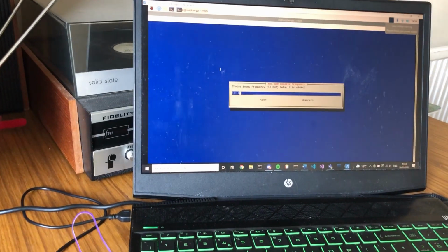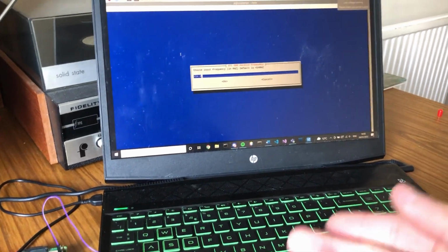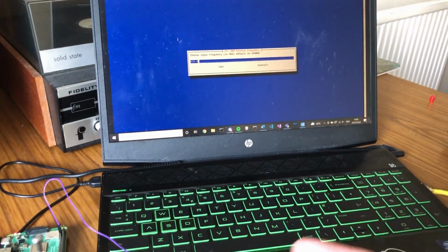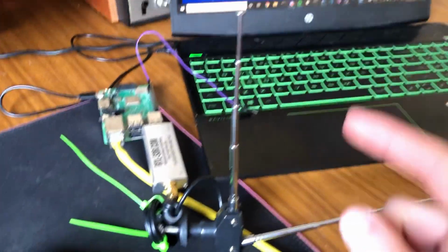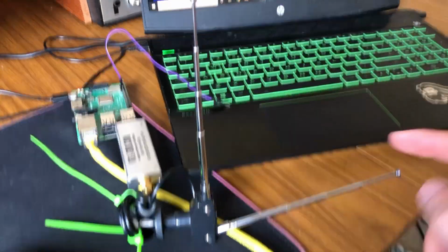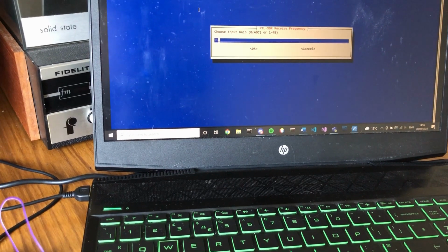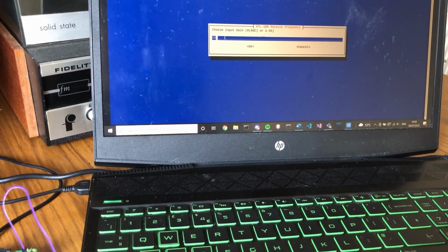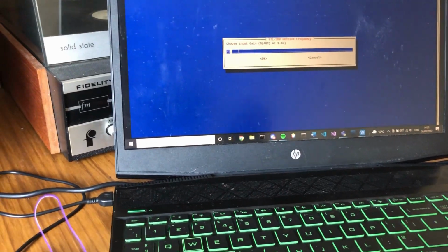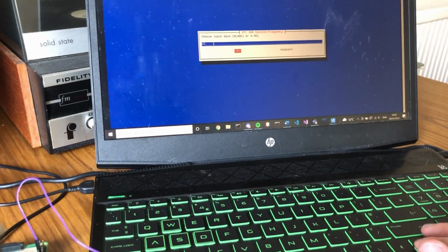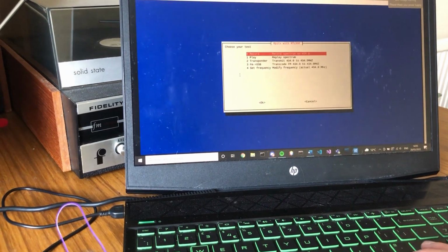And so this prompts for an input frequency. This app basically is the app that captures and records the frequencies we want. So I've plugged in the SDR, which will capture the signals via the antenna, and let's just say we'll capture 434, and we always want the gain to be max, because that's for the outputting of the recorded frequencies, which is to output 434.